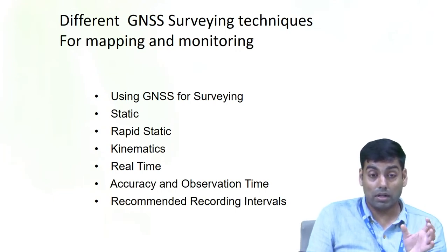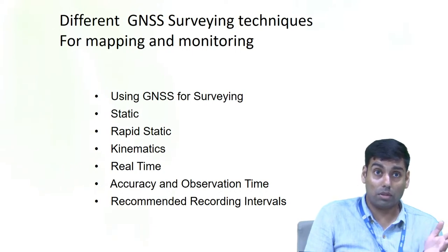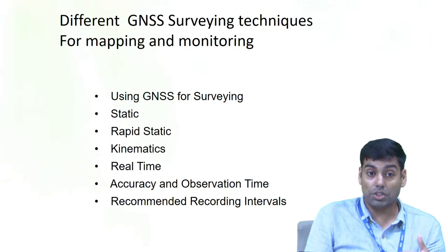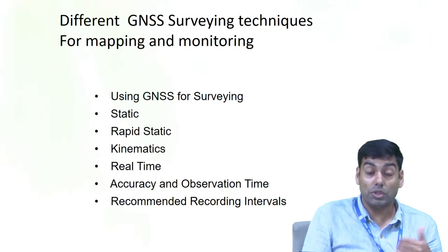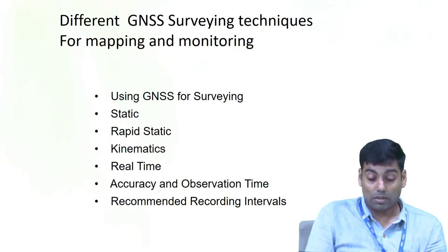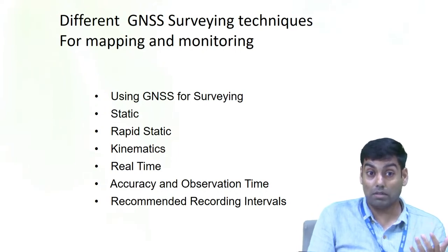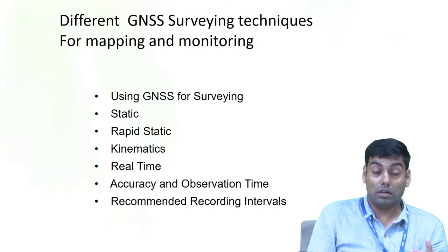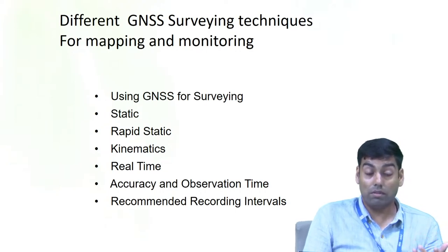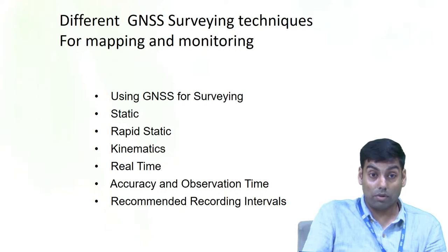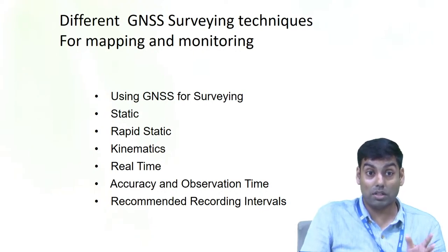Mainly 20-second, 15-second, sometimes 30-second, depending on the energy and how much it is attenuating. So it is necessary to keep a very high sampling interval, meaning 1 second. If 1-second sampling is there, then you can record the earthquake signal when it occurs. But it is not always a good thing, because it takes more storage.